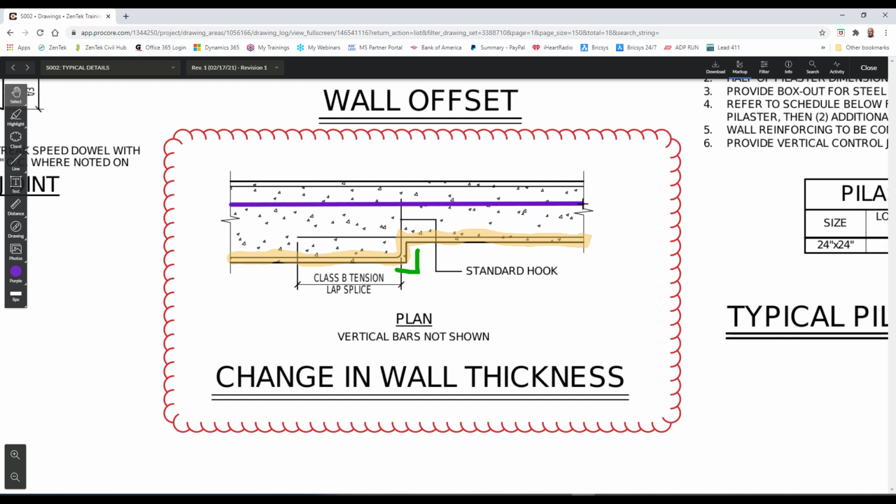See, I can get it nice and straight, and say, okay, I'm going to put in some rebar in there, and then I can actually go in. I can start adding text and labeling things. Right? So I can go in and just create a text box and say, hey, this is number 5 rebar at 16 inches. Oh, see, my typing's bad.